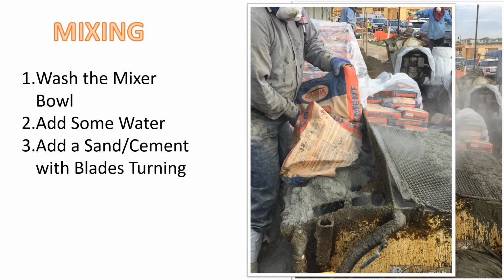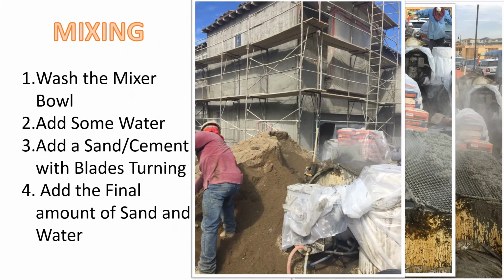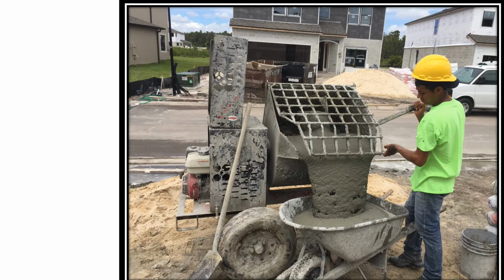Water plays an important role in achieving that consistency. Too wet, the plaster will be called soupy and it loses its cohesiveness. Not enough water and the cement plaster becomes hard to apply and can fail to key properly into the lath. In general, most plasterers seem to prefer a consistency similar to that of soft serve ice cream.